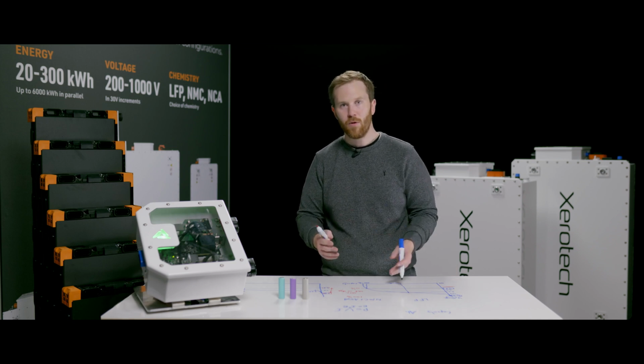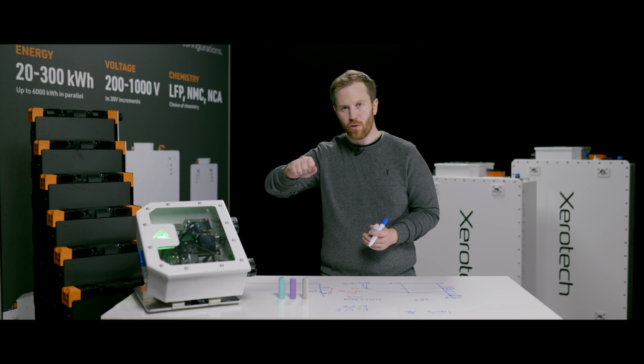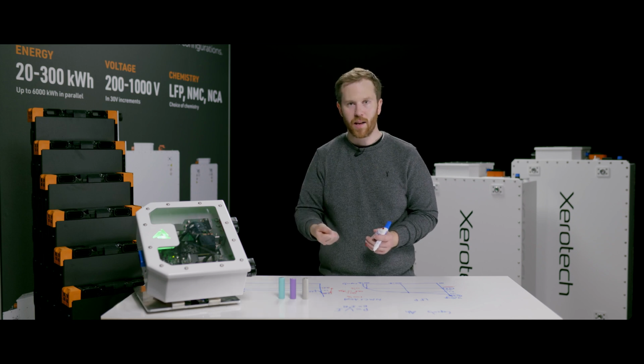So if you've ever seen in the movies, or maybe in your own car, when you turn on the engine and you're cranking that engine, you'll see that the battery voltage drops. You'll see the headlights dim for a second. What's happening there is that a huge amount of current is flowing out of the battery to crank the engine, to turn on the starter of the engine. And that's driven by the internal resistance of that lead acid battery.